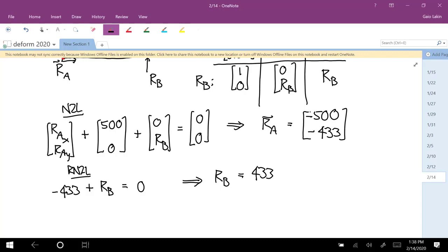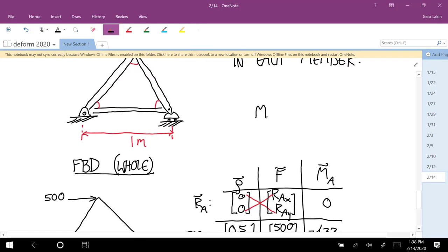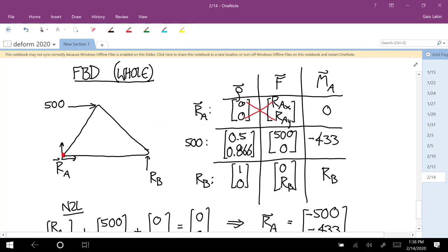Okay, any questions about that? Yeah, so to calculate a moment, it's this row vector crossed with the force vector. And the meaning of that row vector is a vector that goes from the about point, whatever you choose as your about point, to where the force is applied. If you tend to just think of it component by component, let me scroll down. Here you think, okay, there's an X component of positive 1 from the about point here. You go positive 1, you multiply it by the vertical. It's doing the same thing, but it's just doing it with the whole vector. Yeah, I like this way too.